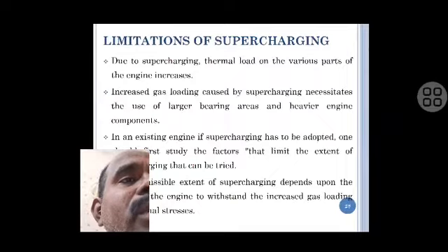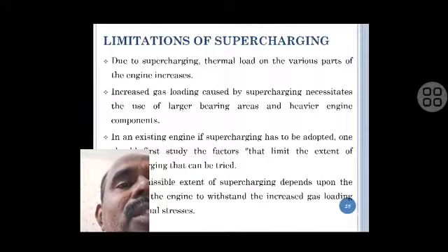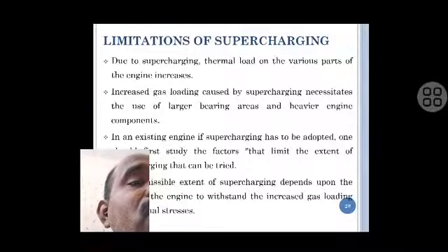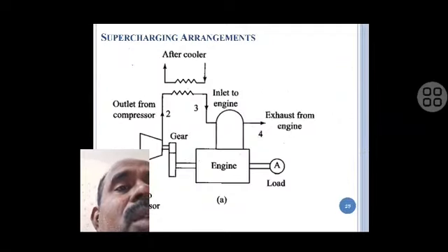Limitations: due to supercharging, the thermal load of the engine is increased. Increased gas loading necessitates the use of large bearing areas and heavier engine components. In existing engines, if supercharging has to be adopted, one of the first steps is to limit the extent of the charging. It also increases the thermal stresses.